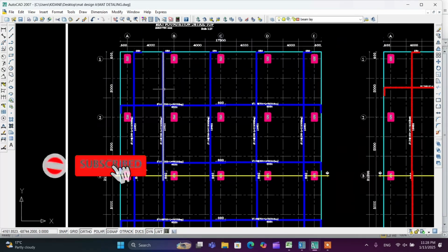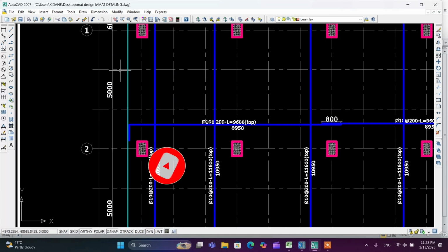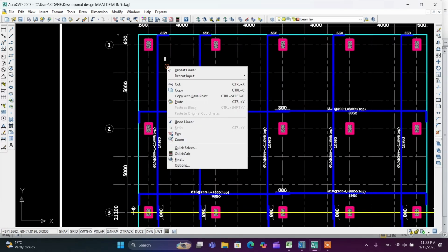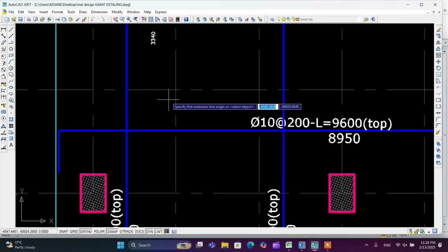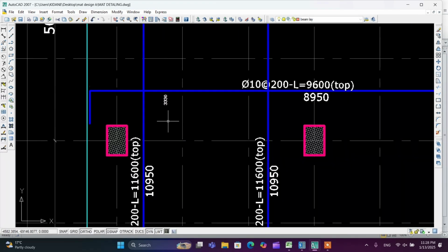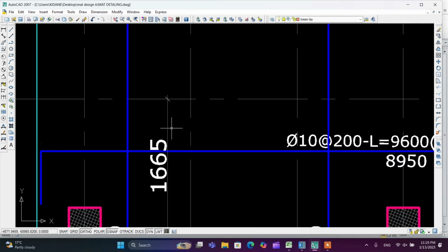So you have to use this total spacing and divide it into 3. So you have to get this value. After that, if you measure all this dimension, the total dimension is divided into 3. So it is equal in dimension. I will show it in detail. So total length is divided by 3. You have to get this equal value, this average equal value. So this total length is divided into 3. So our reinforcement detail is put like this.